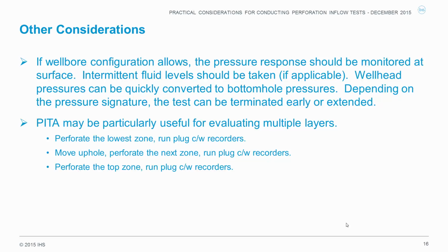PITA may be particularly useful for evaluating multiple layers, and so can be mini-frac. So perforate the lowest zone, run plug with recorders, move up hole, perforate the next zone, run plug with recorders, and continue doing this to test all zones.